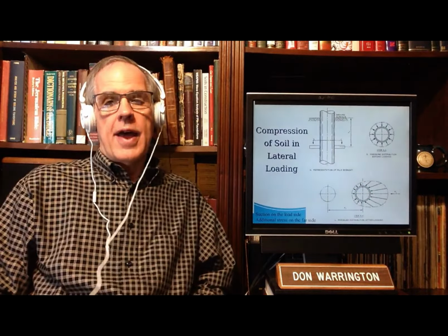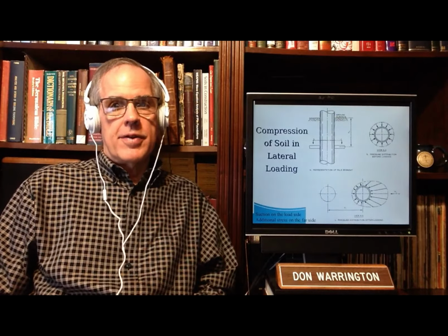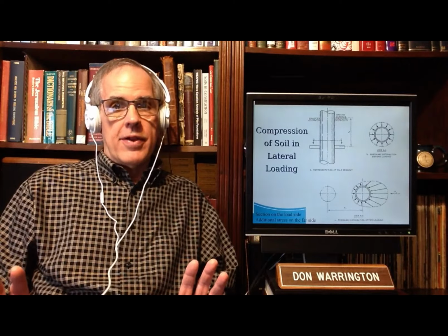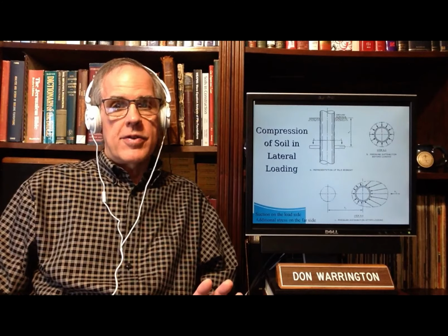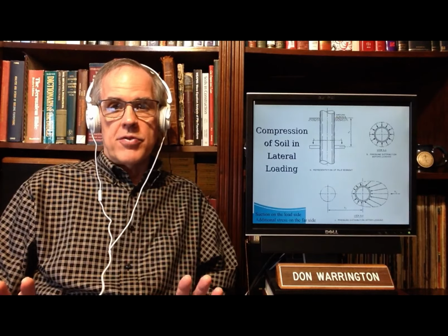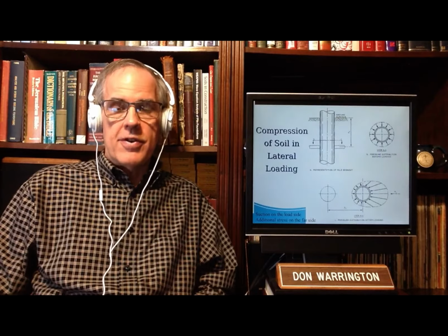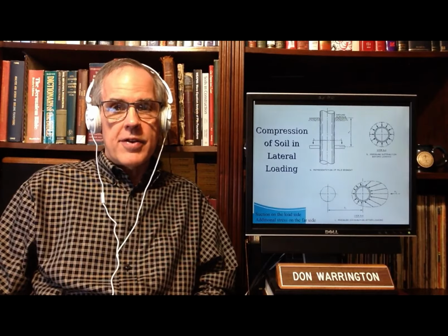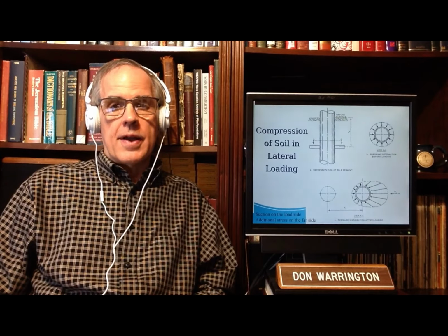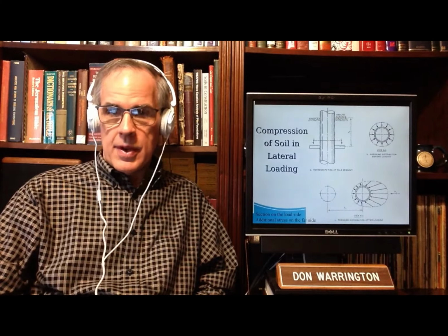That only adds to the complexity of the response of the pile, and that changes as you go down. And on top of that, not only does it change with the deflection, it also changes with the soil type and the consistency of the soil. All of these things add up to a complicated situation.